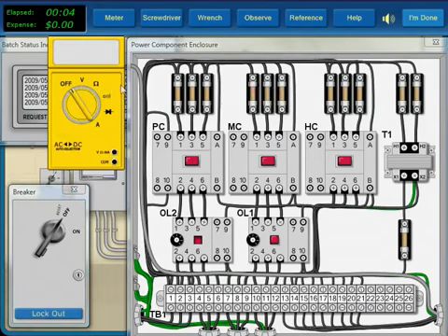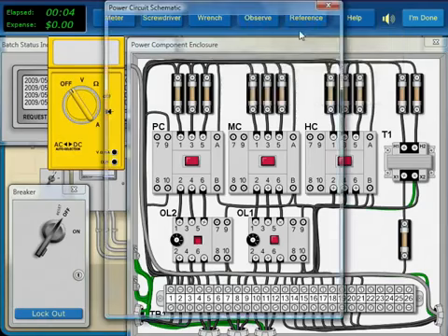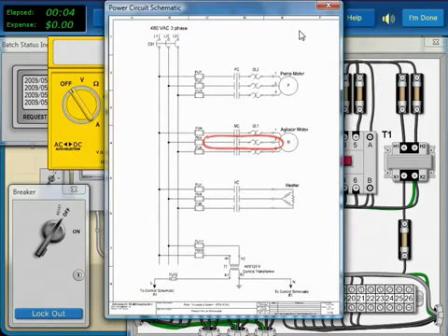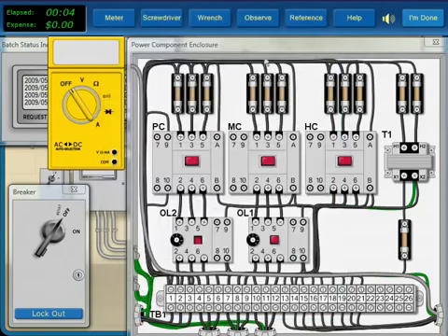We now know that the fault is an open in the center phase, somewhere between the bottom of the fuse and the motor start point. Since there is no obvious probable cause in the new problem area, we will need to perform tests to reduce it. To find an open in a 3-phase motor circuit, an ohm meter is the best choice.